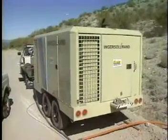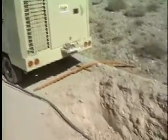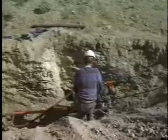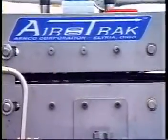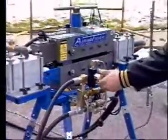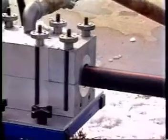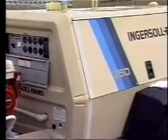A large capacity air compressor is set up at the blowing head location. The fiber optic cable passes through a set of hydraulic-powered tracks that pushes the cable into the blowing head and into the duct system. High-pressure air enters the blowing head and is directed coaxially along the cable into the duct. This creates a high-velocity airstream that drags the cable through the duct.